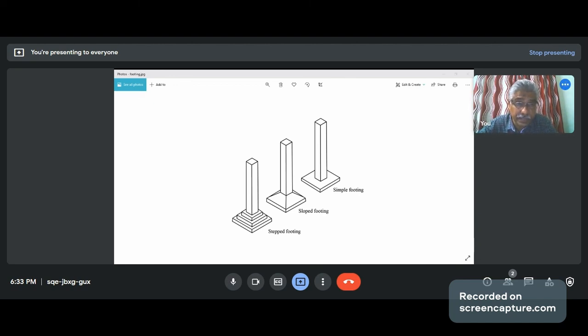Anyway, in isolated footings, experience says that we need to decide the depth based on punching shear or two-way shear or one-way shear. Automatically the thickness required for bending will be quite less than the thickness we calculated based on shearing. So this is the introduction.